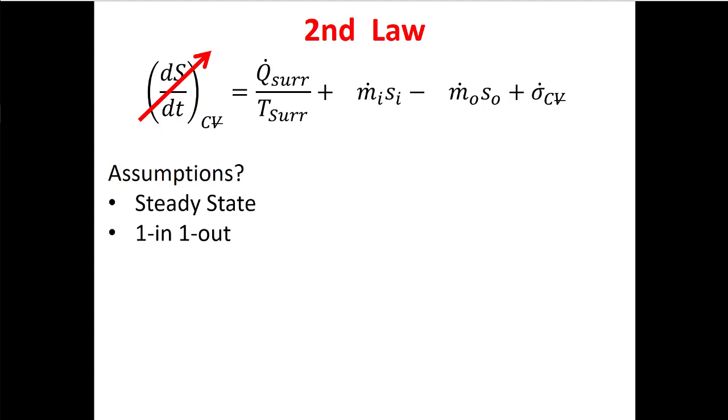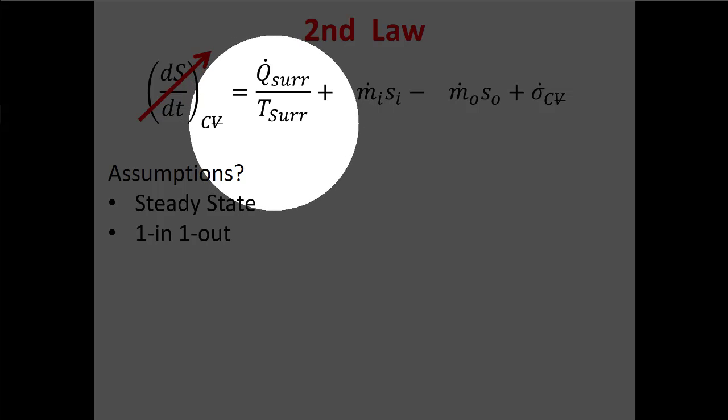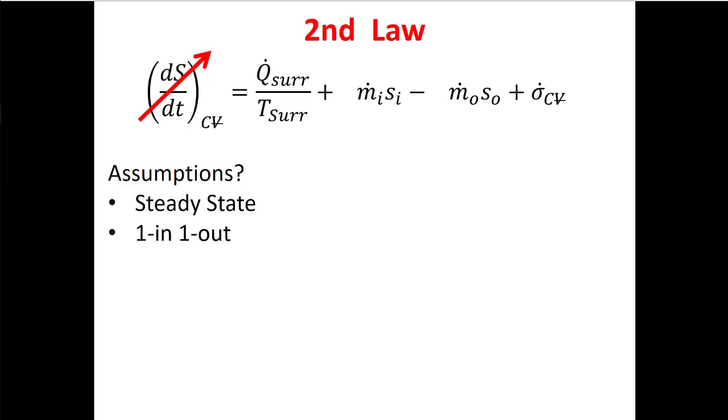But the second thing, the thing that people typically make mistakes on in an exam, is that this temperature on the bottom is not a temperature difference. And anytime you have an equation that has a temperature that stands alone, that's not a temperature difference, you have to use absolute temperatures. It's got to be Kelvin, or if it's an imperial problem, it's got to be Rankine.